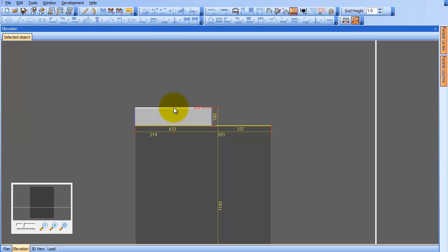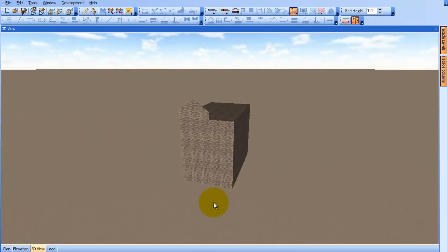Let's make the peak by selecting a point in the middle and dragging it up, using the Z key for a dead center measurement. You can see the vertical line we are using to align with. Then we can create a horizontal line using the Z key to be 100% sure that we are getting an exact measurement. And there we have it, right on the cross point. Now we have a gable on this half of the wall, and here is what it looks like in 3D.